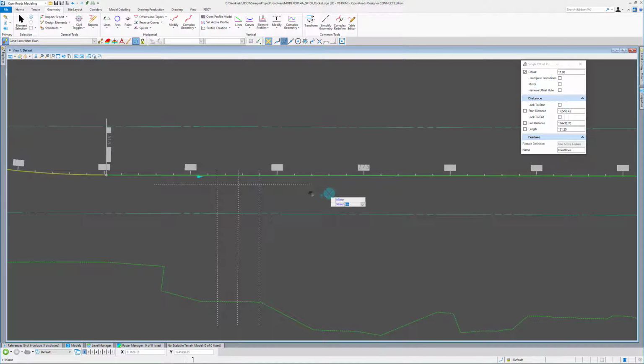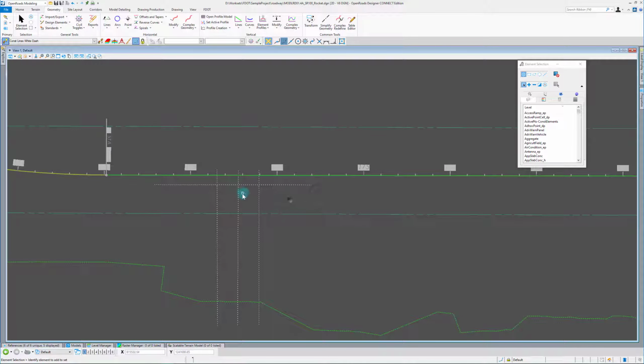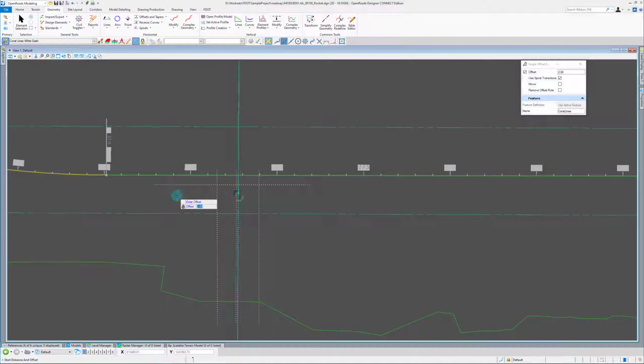I'm just going to make a line here. And another thing I want to do real quick is set up some boundaries for this thing. So it really helps keep everything in place. Like if you move something, it won't let your reference lines move around. I just like to do this. So what I'll do is offset this about, let's say 100 feet, and we'll just say mirror yes.